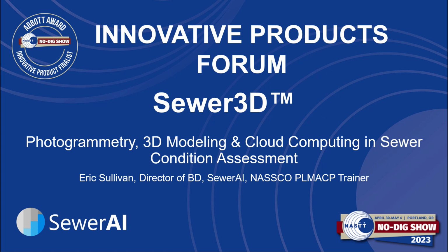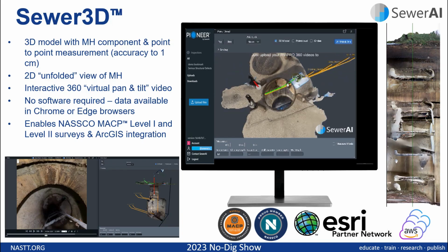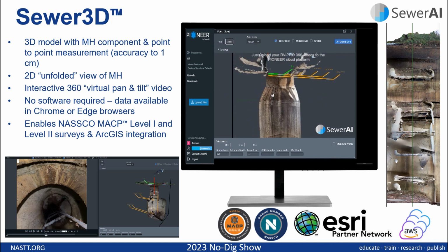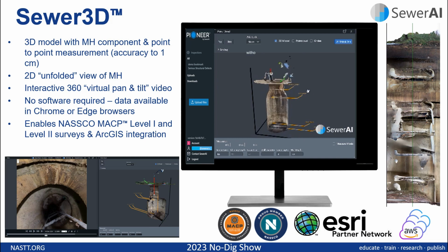My name is Eric Sullivan, and I'm with Sewer AI. What is Sewer3D? Sewer3D is software that takes 360 videos, such as what's captured by the very affordable GoPro Max or any of the other 360 action cameras out there, and upon ingesting a video of a manhole inspection into the Sewer AI cloud platform called Pioneer, our process automatically renders a detailed textured 3D model of the manhole, which enables a user to measure and analyze the geometry of the sewer structure. In this case, manholes and other vertical access points.